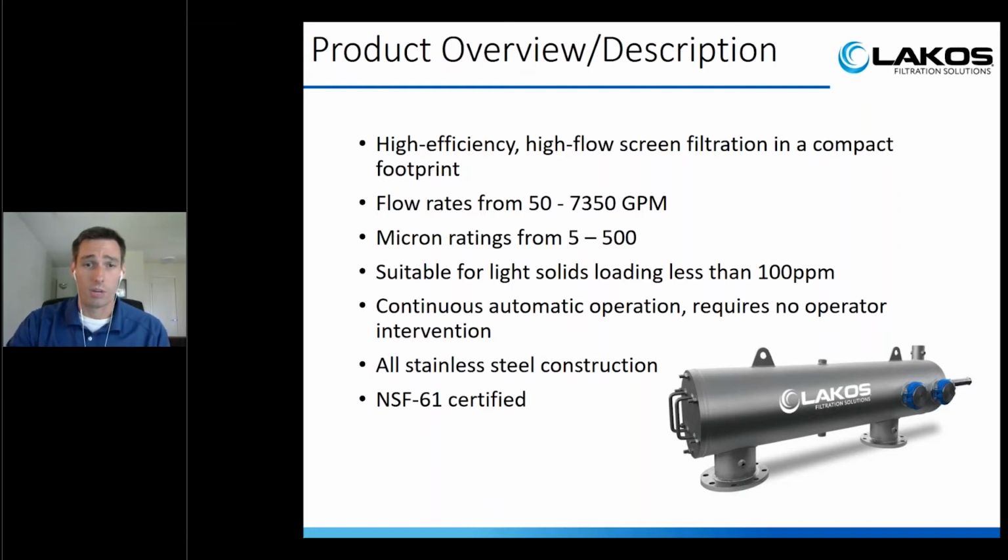They do have continuous automatic operation, so you don't have to have anyone on site monitoring or operating it on a continuous basis. It'll backwash itself on its own based off of differential pressure or a timer. You don't have to have someone there on site watching it all the time.